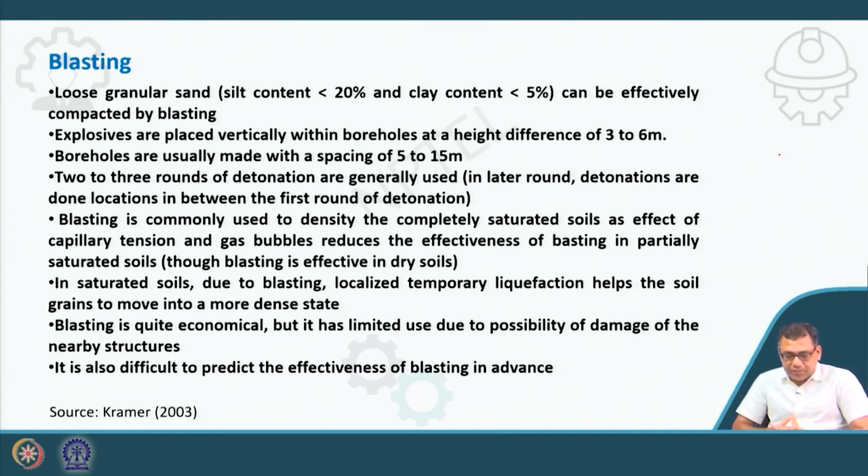2 to 3 rounds. Blasting is commonly used to densify completely saturated soil, as the effect of capillary tension or gas bubbles reduces the effectiveness of blasting in partially saturated soil, though blasting is effective in dry soil.